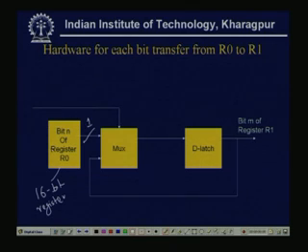Say the register can be implemented by flip flops. So, this is the output of the flip flop, that is only one bit. This one bit is coming to this multiplexer, a multiplexer of 1 and 0. Again this is my enable line.